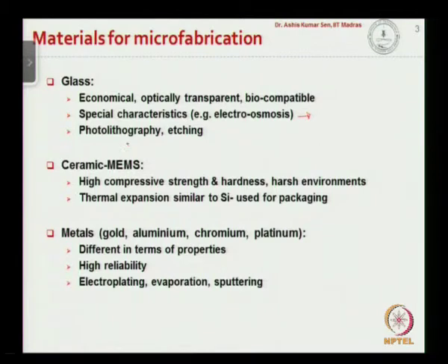The fabrication techniques that we use to manufacture microfluidic devices in glass can be photolithography and etching. Similar to silicon, we can have photoresist patterned onto the glass substrate and create microfluidic channels. We can also do etching of the glass, which would require hydrofluoric acid, HF, etching to create bulk